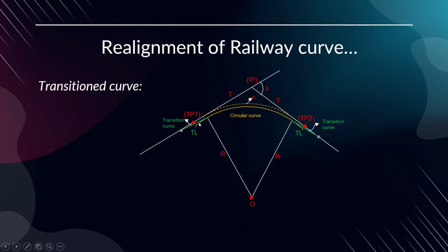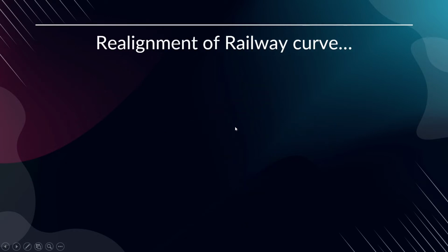At the same time, they inspect by traveling in the train, doing footplate inspection, brake inspection. They will understand how the curvature is performing, whether it is smooth or any jolting is there. With that record also, they will go for the inspection and confirm with the actual existing parameters.